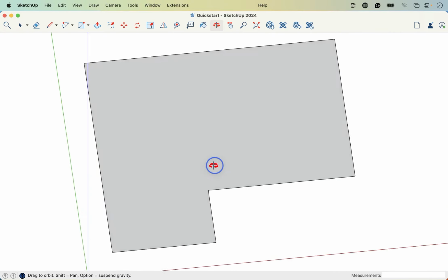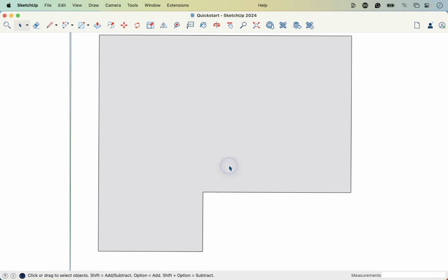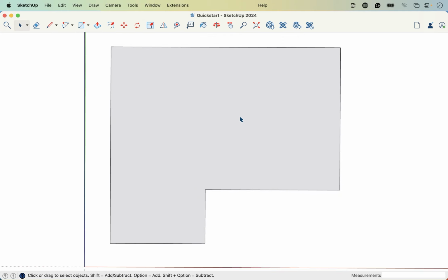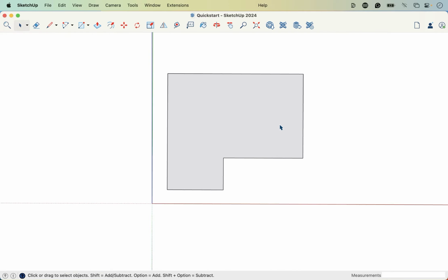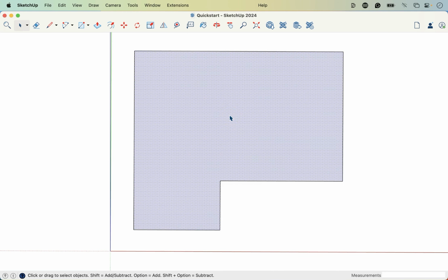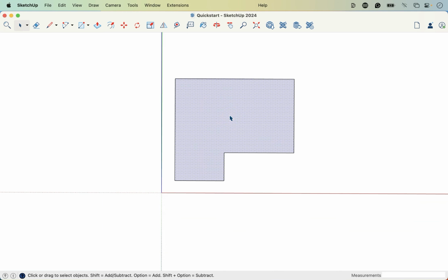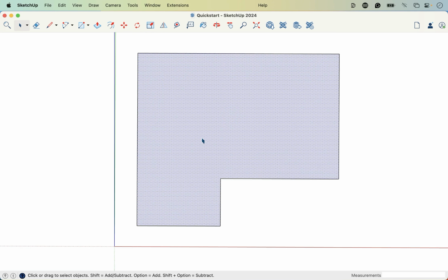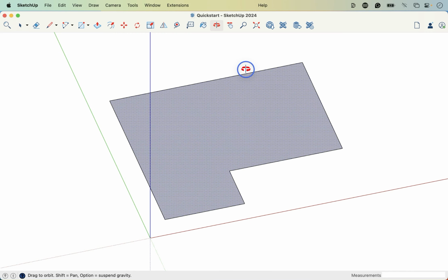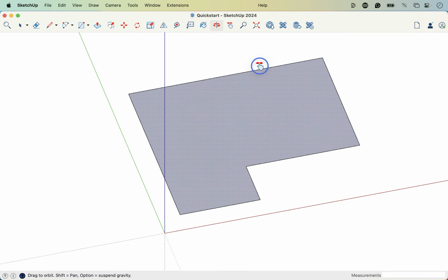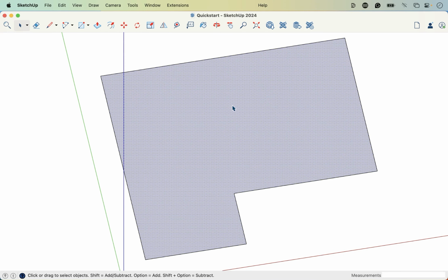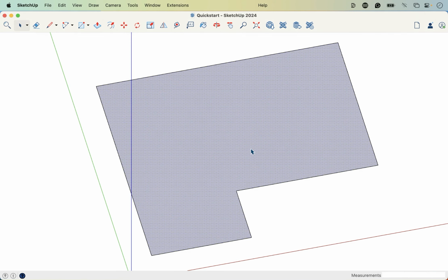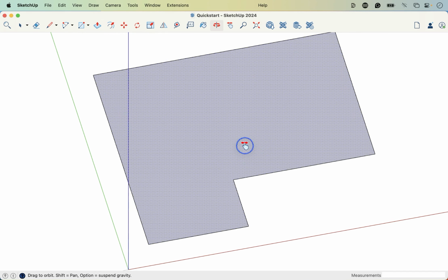So getting your SketchUp driver's license may take a while, but the three main views are going to be the zoom. You can zoom in and out, and anywhere your cursor is, that's where your zoom is going to be. Rolling that center scroll wheel forward zooms in, and backwards to zoom out. Then clicking and holding that center scroll wheel down creates the orbit, and then add your shift key, and that's the pan. It's going to take some practice, but it will become second nature the more you use it. So again, those two icons are up here, but really that center scroll wheel, holding that down to orbit and then adding the shift key to it, is going to be the fastest.